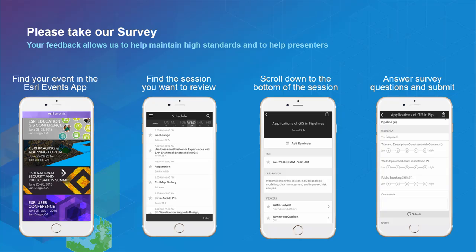So yeah, one way to resolve that is what you were saying, which is duplicate content. Another way is to use symbol layer drawing. It's called symbol level drawing in ArcMap, and we call it symbol layer drawing in Pro, where you can manage which symbol layers draw in what order, and you could manage a controlled stack of that draw order to have it be deterministic.